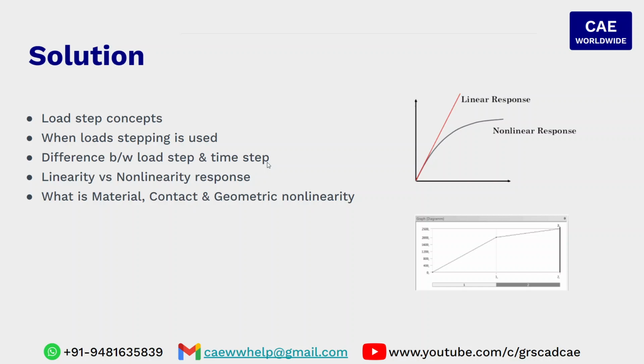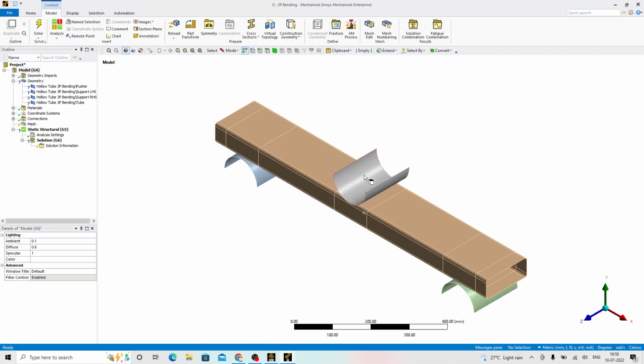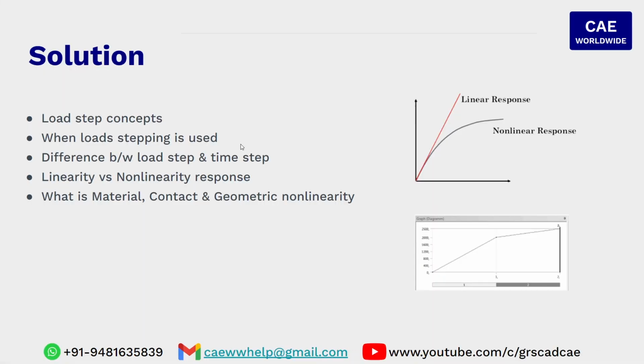Then we'll talk about the load step concepts, and when to use load steps. If we take the example of a 3-point bending, we have a hollow tubular structure at the center which is supported on 2 supports, and the load is applied from the top. Application of the load and retrieval of the load is a 2-step process. This is called load stepping. How do we deal with that load stepping, and how to make the loading gradual, uniform, and capture the behavior of the tube throughout that bending process will be discussed in detail when we talk about the solution process.